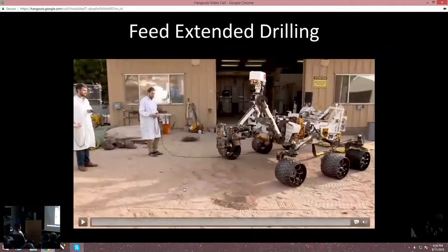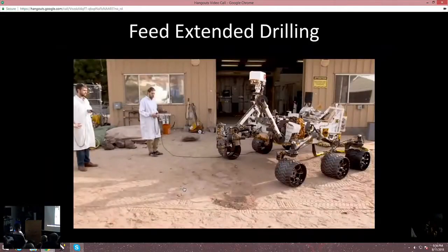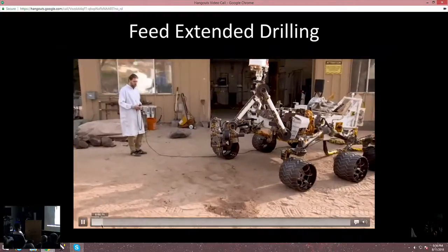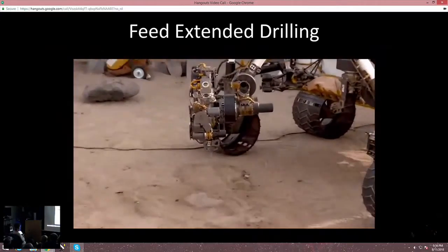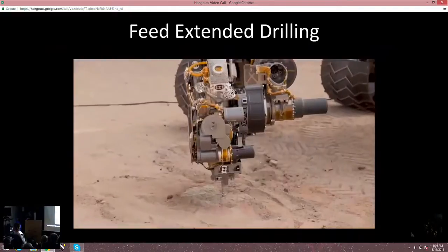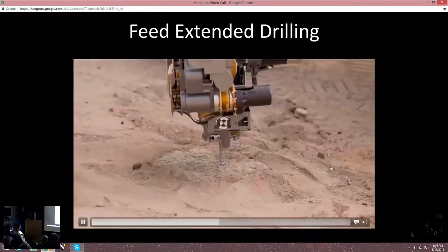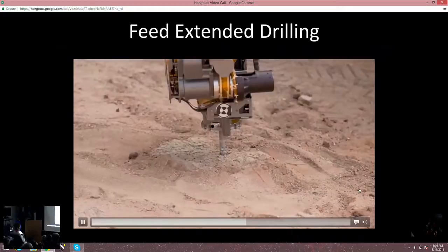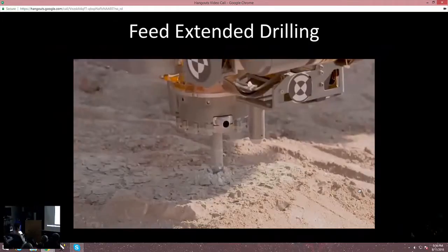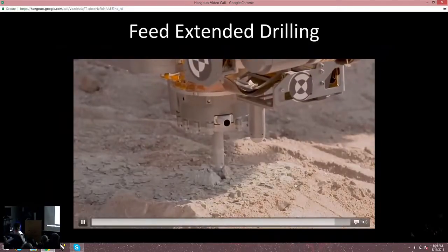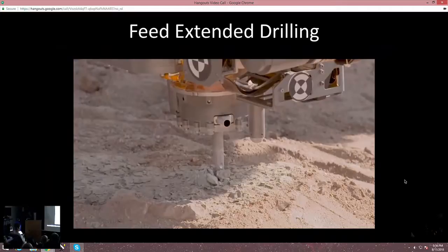Here's a new video that was taken sometime this winter while we were testing out our new capability, and you'll see the differences in how we drill now. Here, the drill is already extended past those stabilizers, and we're moving the drill bit directly onto the rock. Now the bit is directly in contact with the rock, rotating and percussing. Then we have to pull out once we are in the hole and retract safely from the rock as well. All of that is done with this huge robotic arm instead of the single mechanism designed specifically to do this.